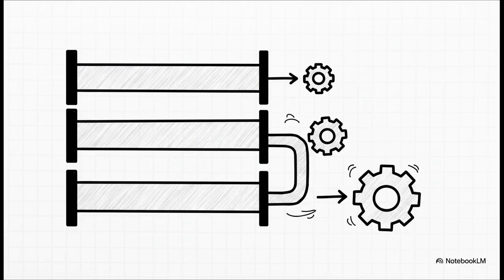Practically speaking, this means every Boolean function you write has to be independently simplified to fit its specific section. If a function is too complex and needs more terms than you have available, well, you might actually be forced to cascade into a second section just to implement that one single logic function.